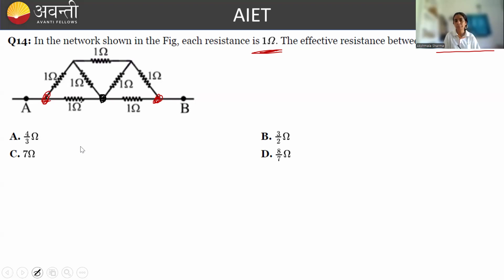जैसे देख लो यहाँ पे, we have to calculate R equivalent across A and B. So draw a line joining these 2 points, जिसके across आपको R equivalent निकालना है. तो ये line हो गया ये वाला. This is the AB line. है ना, and then draw a line perpendicular to it such that it is bisecting the system. If that line can be drawn, then, यहाँ पे अगर मैं draw करूँ तो ये एक ऐसा line है जो कि हमारे resistors के system को actual में bisect कर रहा है ना. So this is the vertical line of symmetry.